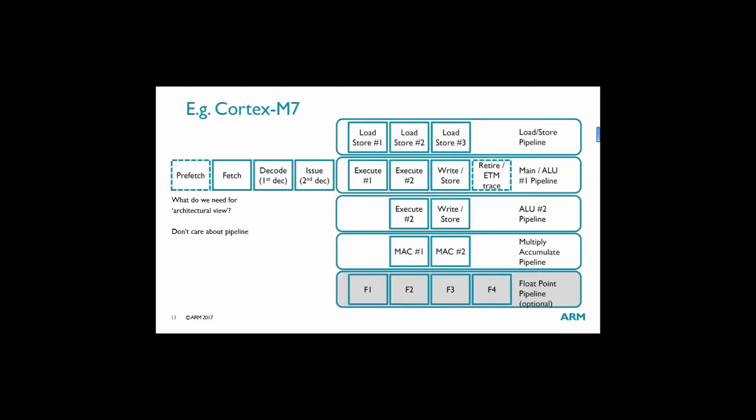Because for the register file, the architecturally committed values live in the register file. And because this is an in-order processor, all writes occur here in the WR stage across all these functional units. And the architectural values are updated when an instruction reaches this WR stage. So all we need to reconstruct our architectural state is the instruction, whose opcode will be observed as it goes through the prefetch, fetch, etc. stages of the pipeline and reaches the WR stage.